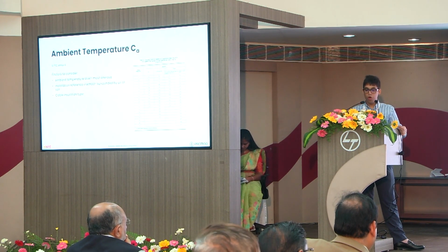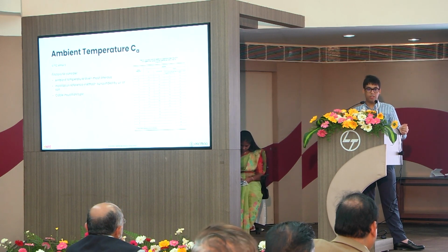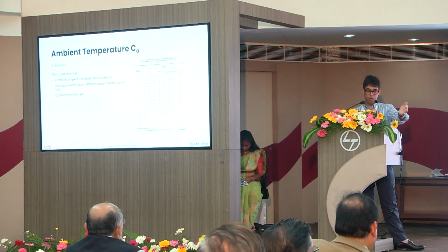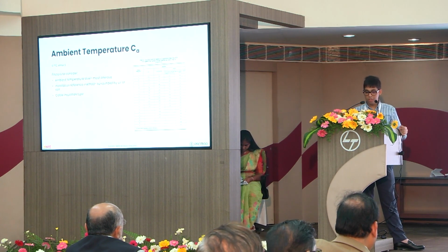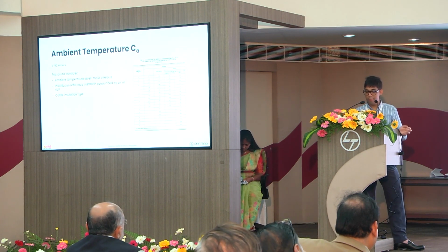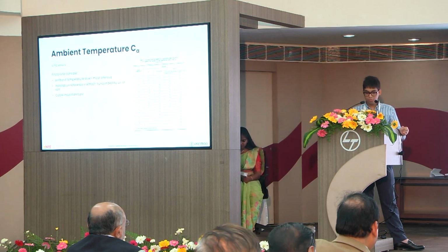So again, what is the most onerous ambient temperature in the condition? If it gets cold in the winter and hot in the summer, you have to take the hotter temperature. Again, ambient temperature correction factors are different for the different types of insulation. PVC and XLPE will have a different correction factor, and mineral insulated cables will have a different correction factor. Also, there's that. And the insulation reference method, of course.